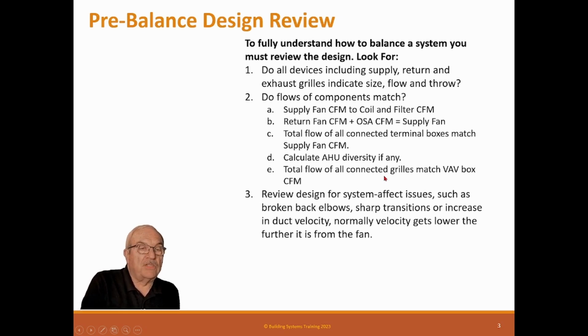Review the design for system effect issues such as broken back fans, sharp transitions, or increases in duct velocity. Normally velocity gets lower the further from the system fan, at least it should. So system effect is where fittings or other things cause excessive pressure drop, like a broken back fan. That means basically that an elbow turns the opposite direction of the fan rotation. Why that's important is because the air has to stop, converting all this velocity pressure to static pressure, and then turn the other direction and then regain velocity pressure, and that actually takes horsepower.